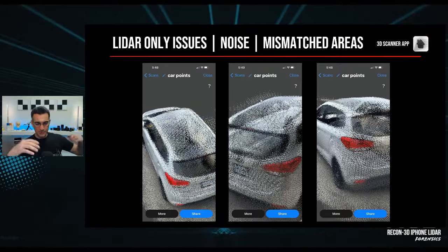And so loop closure, Jared had talked about that, or he mentioned it. But basically, when you end up going around an object once, twice, or three times, if you don't have loop closure, it's about the same as walking in a straight line. Okay, it doesn't recognize that you've passed the same area, and it can't adjust those two surfaces on top of each other. Basically, what you're getting is an accumulation of errors across the entire scan. And so as you continue, your scan ends up drifting. Okay, so when it should be here, you start accumulating small errors, and it drifts.